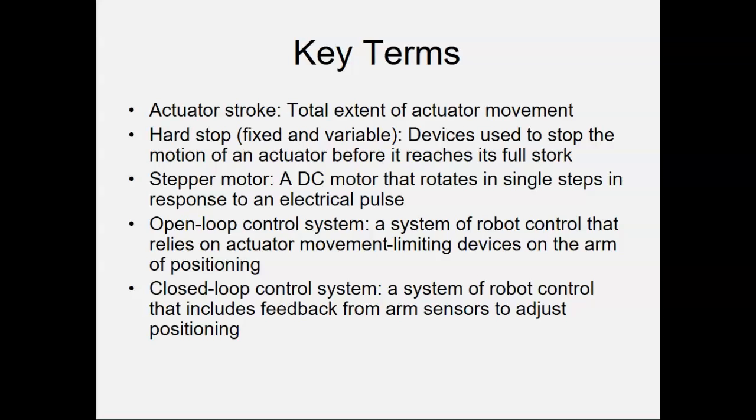No, actuators are what would actually make the wheels turn. We use them a lot in hydraulics and pneumatics. That's why my brain is stuck on that. But essentially, any machine that creates movement is a type of actuator. Actuators come in three types. You have partial rotation, full rotation, just like a clock or a motor, and then you've got the linear actuator that just has the ability to move in and out.